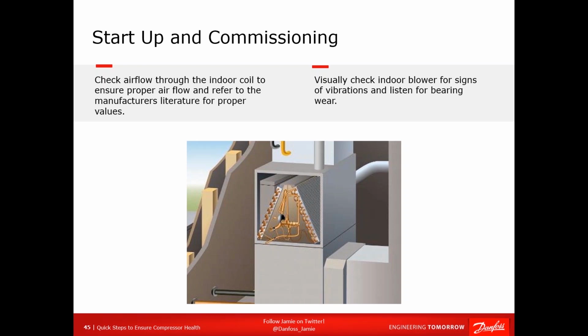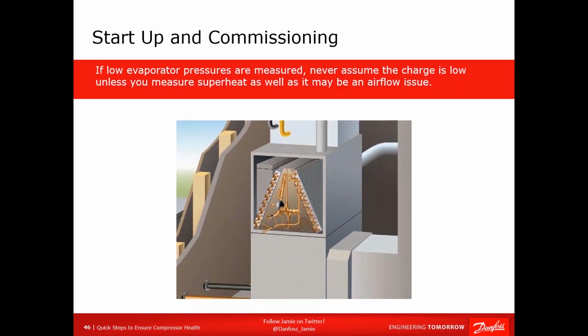All right, because if you have poor airflow, you have poor air conditioning. You have poor dehumidification and cooling. You are not going to have a happy customer. And nothing else you do is going to improve the system until you correct that airflow. Trust me on this one.